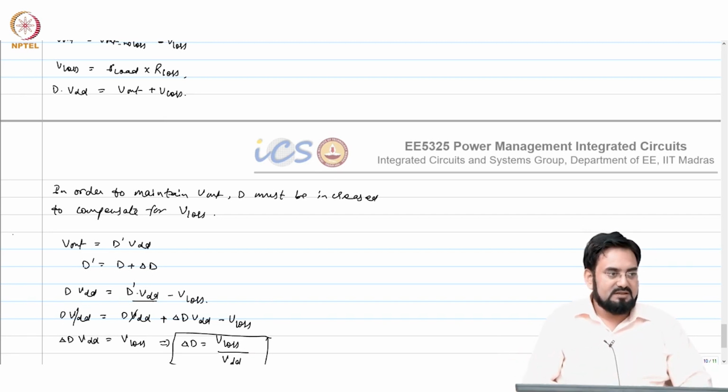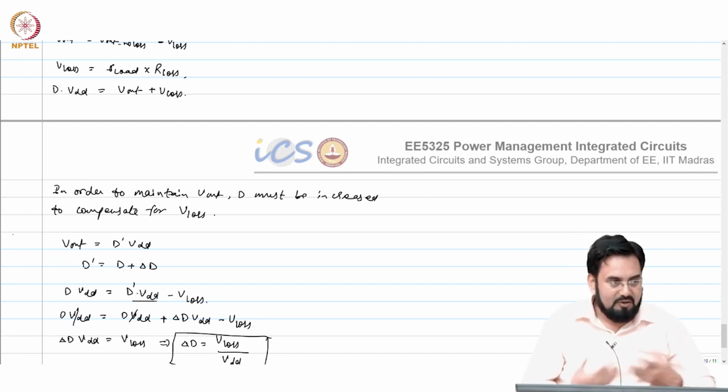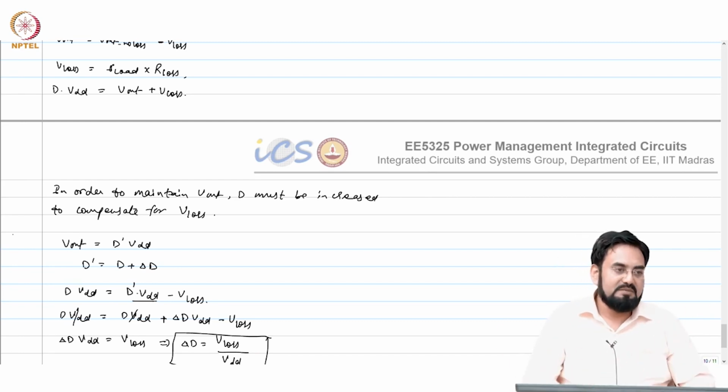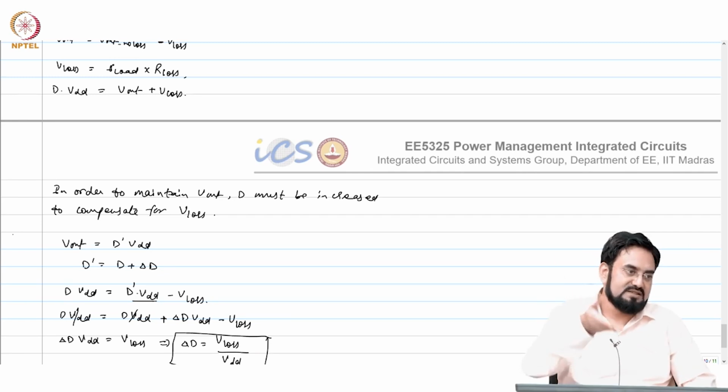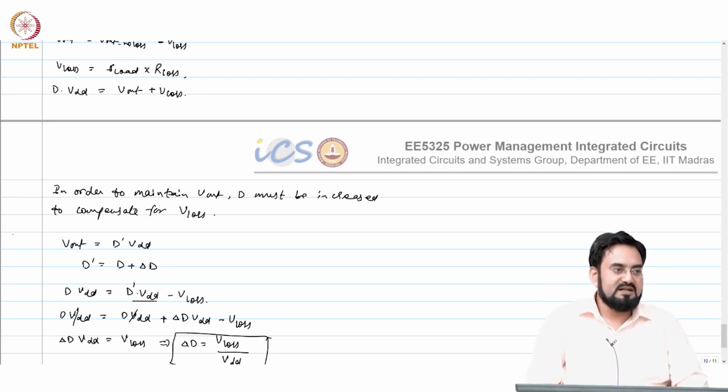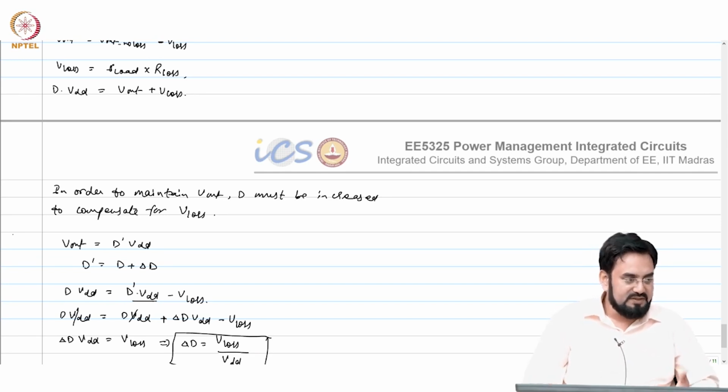And then you go back again to the negative feedback compensation, all the concepts will apply here, because now in the loop you have an LC filter, and LC is a complex filter. So, it will have complex poles. So, now you have a double pole and a complex pole. If it is a very high Q, then at resonance you will get a 180 degree phase shift right away. So, inherently it is an unstable system if you simply connect the negative feedback. So, you need to stabilize it, and we need to compensate it.